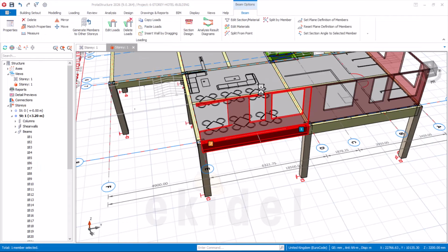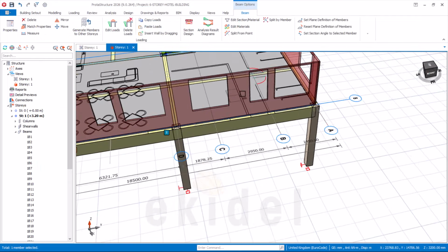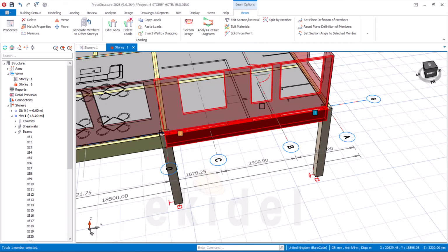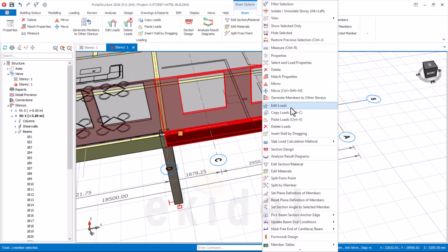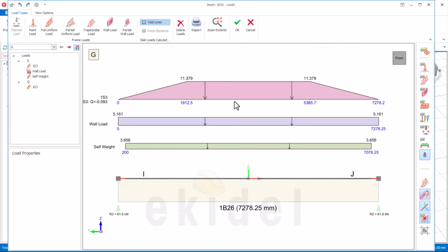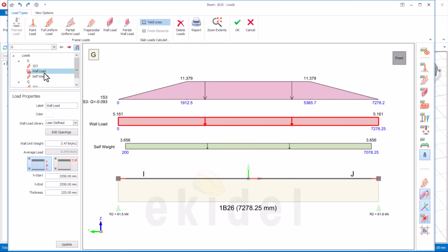Okay, that's fine. Then in this case, we now remove this particular one that is at the middle here, for us to achieve what we have. So come now and then edit. Always work with the story floor plan you are working with, right? We are using the ground floor to model the windows on the first floor, which is wrong.